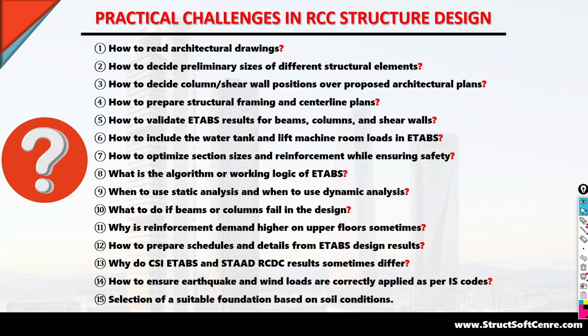How to do the calculation for earthquake loading, how to do the calculation for wind loading for a tall structure. For medium rise and low rise structures it is easy. But for the tall structure, how to deal with it? How to perform the stability checks for torsional irregularity, in-plan irregularity, overheight irregularity, lateral deflection, lateral drift, maximum and minimum deflection, and buckling analysis. All these things are very important to perform.